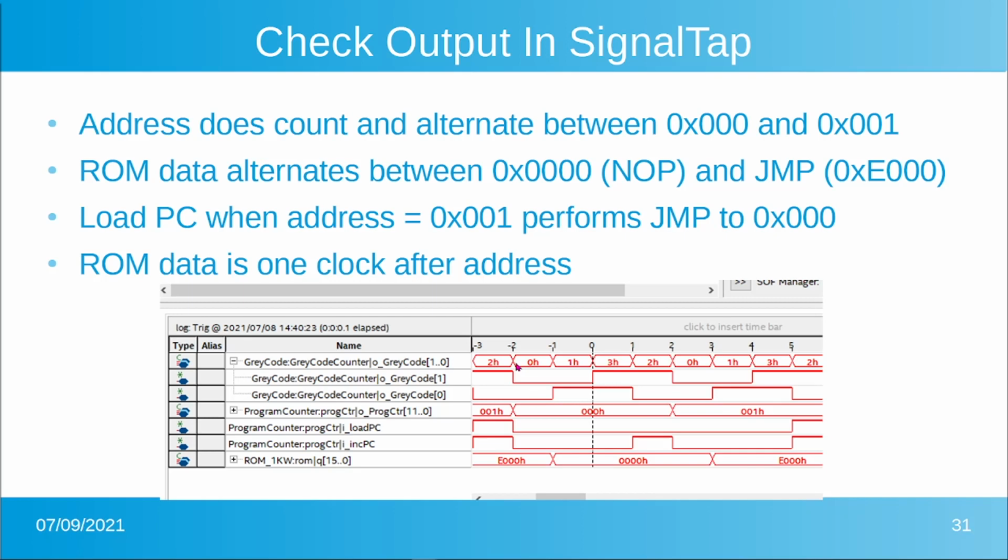Now again, this is a state machine timing logic analyzer, let's say, and so of course it doesn't have detailed time. You don't know exactly how many nanoseconds this is, but it's capturing on the clock what the values of all of these registers are on that 50 megahertz CPU clock. So you now own many channels, a pretty deep logic analyzer that you build into your design, and then you unbuild it by just shutting it off when you're done debugging.